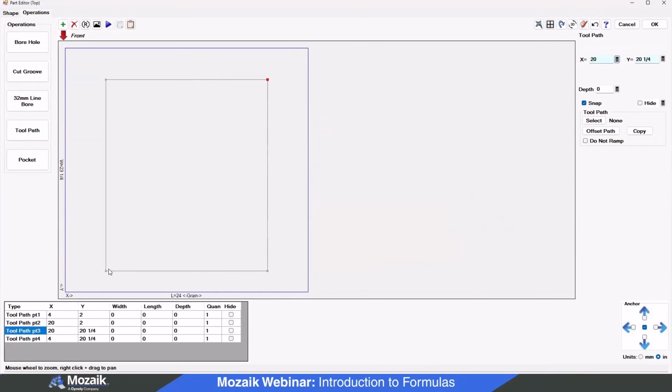Lastly, we need to set the depth, and we need to select a tool. Now, if I was to select a tool and set a depth to this, there's a few different variables we could use here. We could use part, like top dot thickness. We could say the part thickness, but I also would have to account for the diameter of the tool. So right now we're going to be cutting on the center line of this machining line here. I could add that into my formula to account for the diameter of my tool, but I want to show you guys a quick trick.